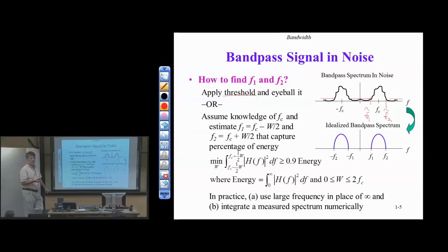where the center frequency would be. It's based on the standard. It's somewhere between 2.4 and 2.499 gigahertz, based on which subchannel you pick up in there, which 20 megahertz subchannel, you know where the center should be. You also know if you're looking at the whole ISM band at 2.4 gigahertz, the center frequency is going to be at 2.45 gigahertz. So you kind of know what you're looking for in advance. Go ahead.